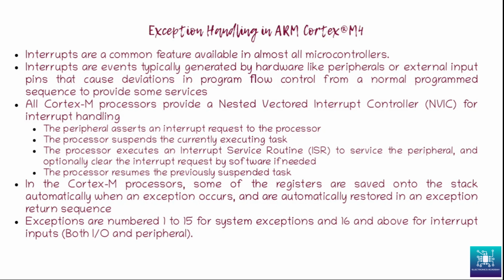The interrupt service routine gets executed, and all the registers are restored to their previous values, that is, before leaving main, and the execution in main continues as if nothing ever happened. In the sense, the main doesn't even realize that an interrupt had occurred.